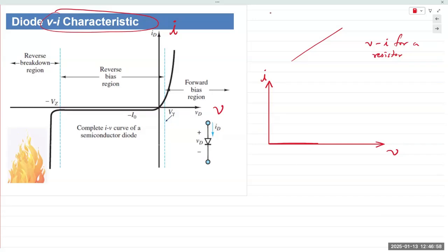Remember, we talked about the depletion region, right? The depletion region is a barrier that is built in, meaning the moment we create the PN junction diode, holes and electrons diffuse and recombine. There's a region that is depleted of all charges, and then it gives rise to an electric field. That electric field opposes any further diffusion of the charge carriers, and so it stabilizes to a certain level. Depending on the material we use, that level is fixed. For silicon, it's about 0.6 to 0.7 volts.